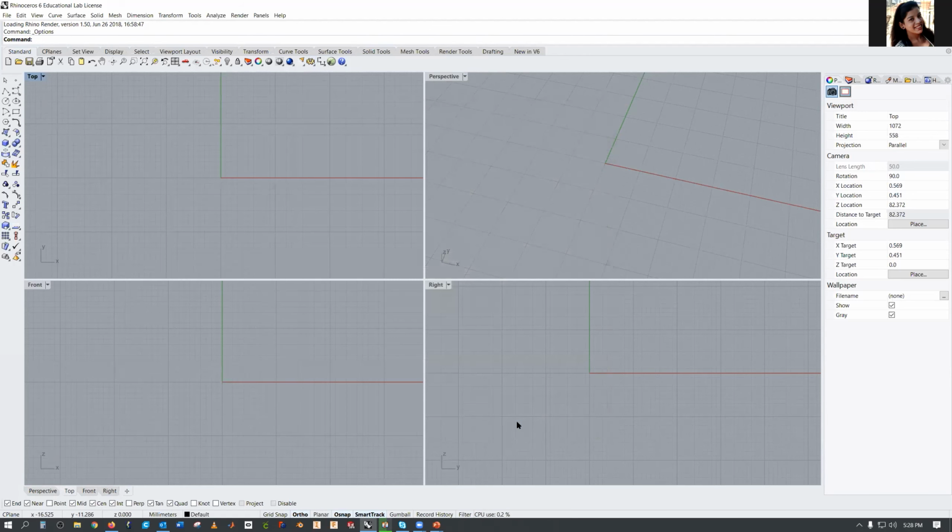I'll click OK. And now, let's say I go over here to polyline, and I'll just start drawing a line. If I just start drawing, you can see it's doing weird things. It looks like ortho is on. So I'm going to go down here at the bottom, and you see that ortho, orthogonal, so only in 90-degree increments, is selected. So now I can turn that off. And now I'll have free movement.